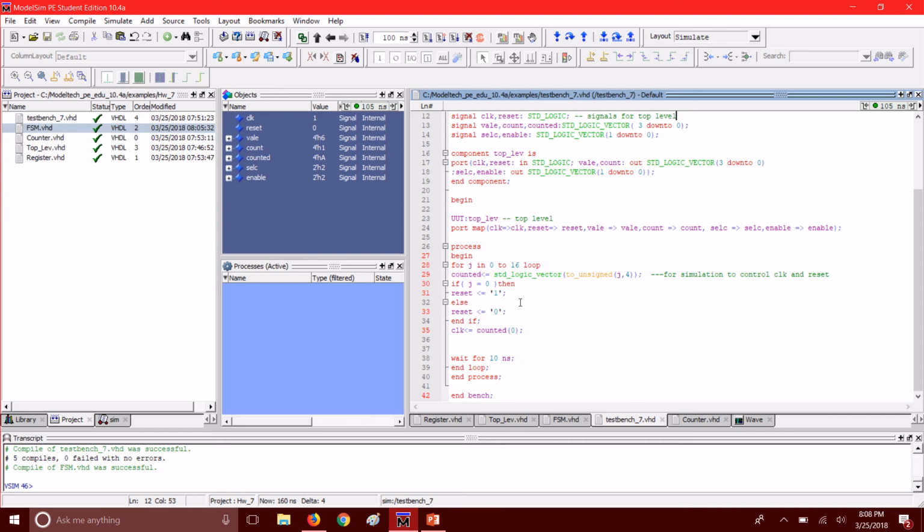And we send a reset to the FSM so that we can properly establish that all the components are at 0, 0. And it waits 10 seconds between each loop cycle. This helps me make sure that I can assign the least significant bit to clock, so I can iterate a clock. So let's go ahead and get to the waveform.